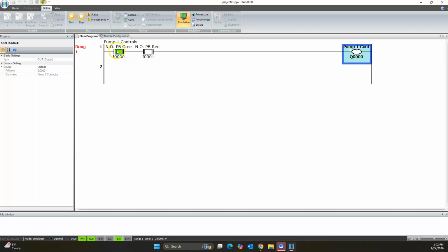I set these up. I'm going to reset this as well. So we'll just go back to basics where we've let go of all the buttons. Okay, cool. We've set these up as normally open contacts, or what I will say is a make instruction. So a make instruction, when we see 24 volts at an input, a make instruction will then make logical continuity. That's why we call it a make instruction.